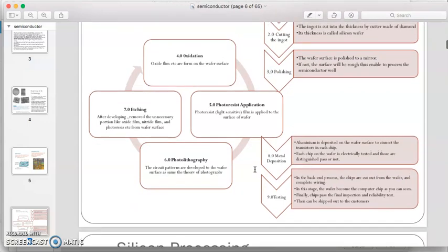After finishing all the layers, we go to the third phase: deposit the metal to connect each component inside the chip. Then we test the chip, so we can identify which chips are okay, and the defective chips will be marked and taken out as waste.